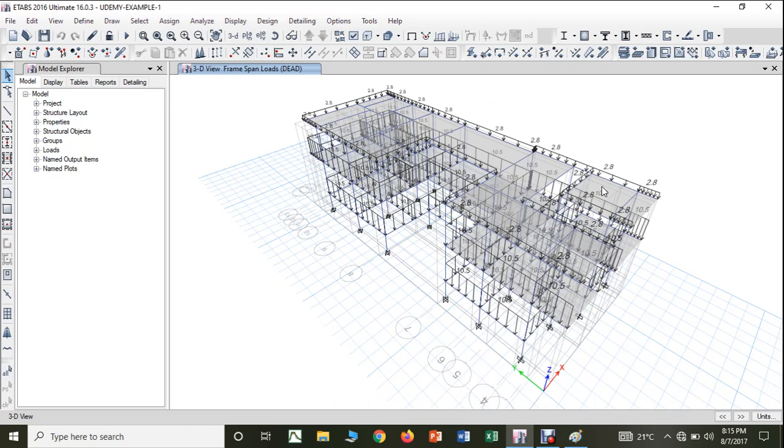This is about live load. But when it comes to the slab, along with the self weight of the slab and the live load on the slab, an additional load of 1 kilonewton per meter square has to be considered, which is called floor finish load. Because when you come here, the slab will be there, and above the slab you will be using the floor finish.